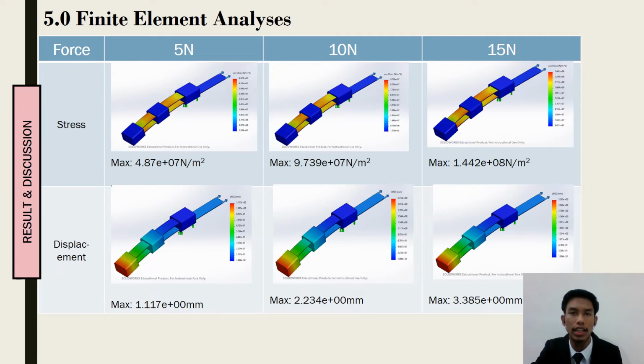We can see the different stress on the red zone between the top nickel strip and the bottom nickel strip. On top, the stress is more on the middle fingertip, while at the bottom, stress occurs at the front and back fingertip. For displacement, the red zone occurs at the front fingertip, which means the higher displacement happens at that point.